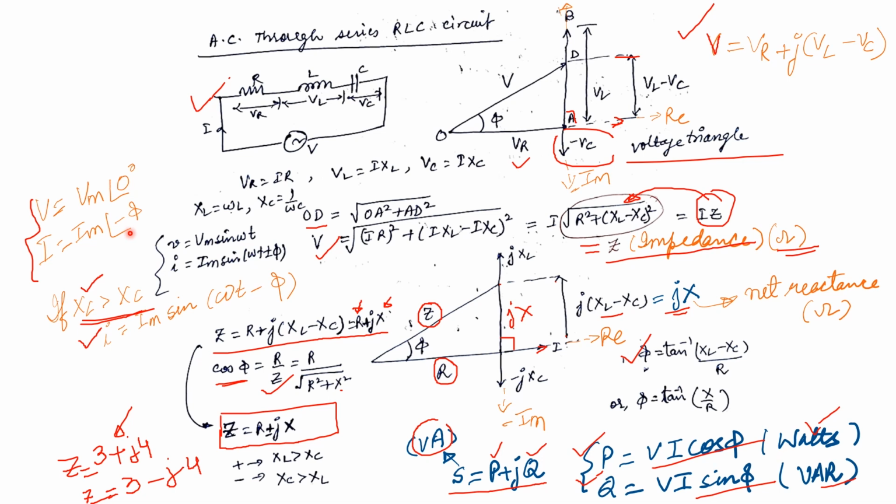That is, whether the power factor is lagging, leading, or unity can be obtained by looking at this value. So here I can see it is minus 5. Minus indicates that the power factor is lagging, and this is the angle by which it is lagging. So the resultant current is lagging with angle minus 5.